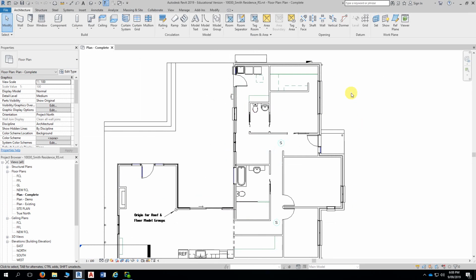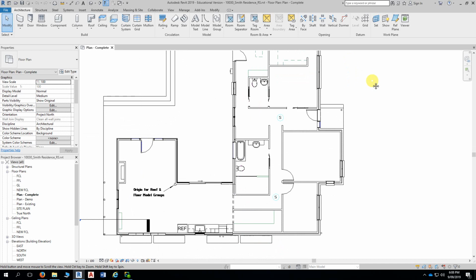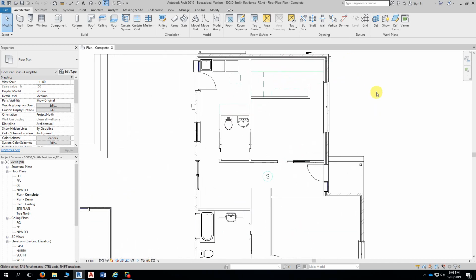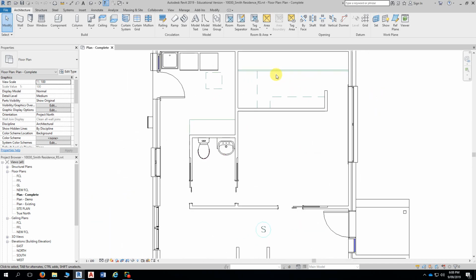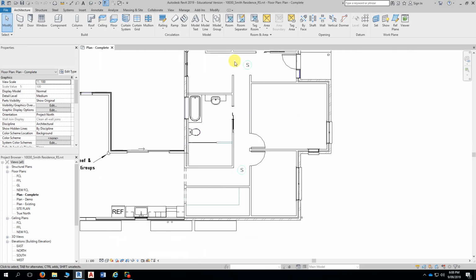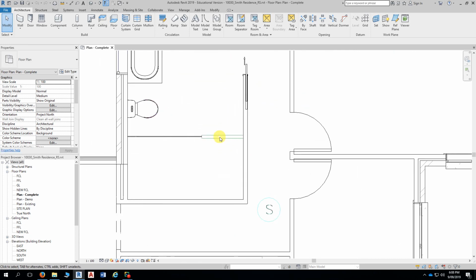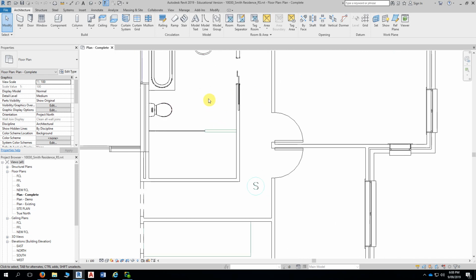What's still visible from the AutoCAD plan itself is this green line work here. Initially we're going to add detail line work over the green lines. Now again, this outline here, this one here, and this one down here, we're actually going to add as what's known as a masking region. We'll have a look at those first.